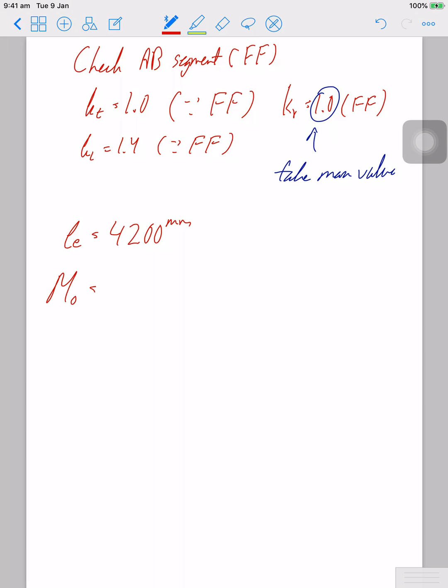So if you put it in your reference buckling moment formula, it wouldn't be different. It would still be 189 kilonewton meters, particularly because your L_e was the same for segment CD and AB. So if your reference buckling moment is the same and your section moment capacity remains the same, your alpha_s is also unchanged.